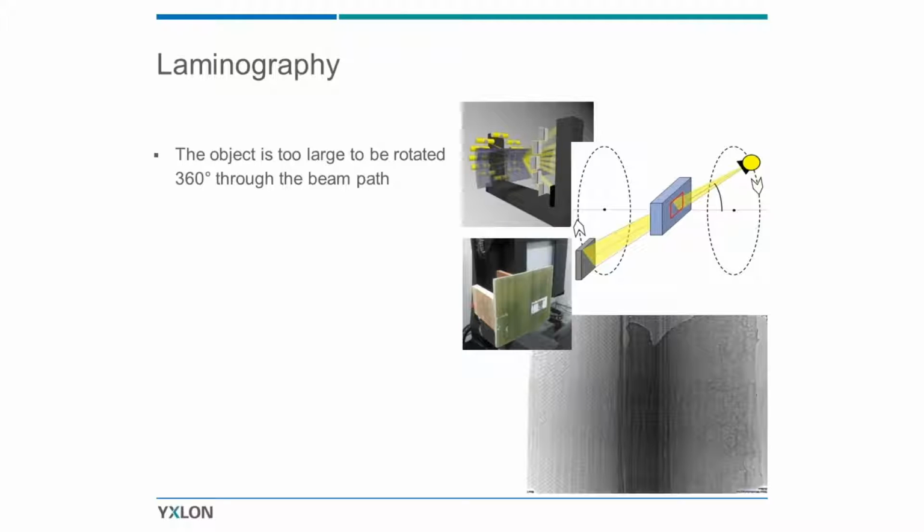And then there's laminography. That's a technology where you have your sample in the middle and you rotate the tube and the detector around the object, and you take different shots from different angles, and the software would then stitch it together and reconstruct a slice through a certain area. This is used when you have large parts and you want to look inside and have more information about the depth of the defect.